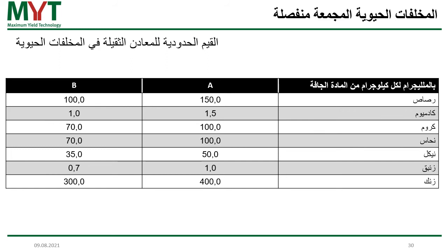We do not look at the nutrition side of the compost. We look at the limiting values for heavy metals. You can produce compost of different qualities. If you have quality A, you are allowed to have a higher content of heavy metals and pollutants. If you go to compost quality B, it's more strict. This also determines how much of this compost you can bring out to the fields per hectare, per year, or in 5 years. It depends only on the heavy metals.